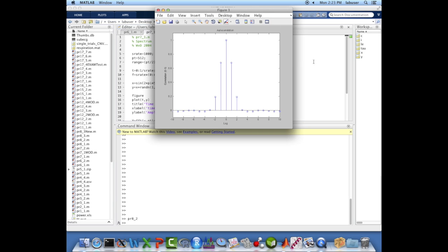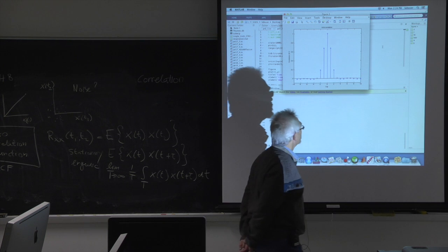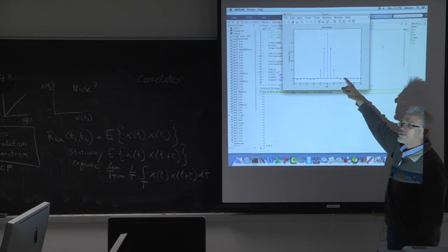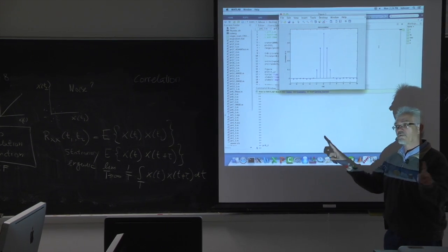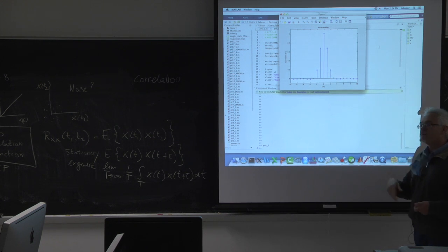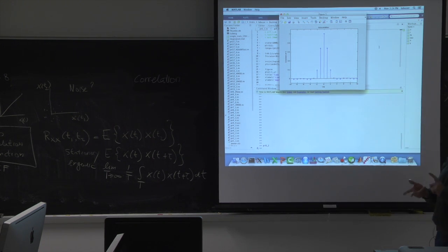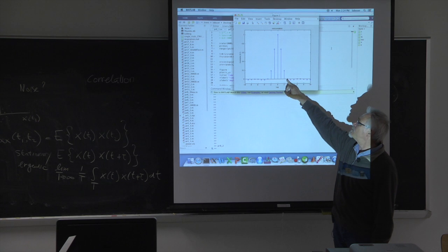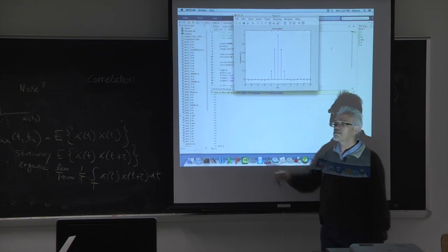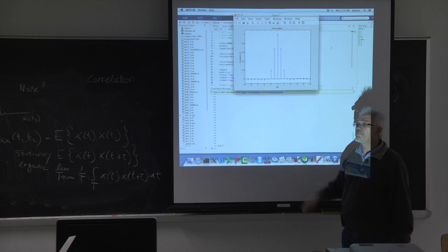If you run this program, it will compute, using the random command in MATLAB, the output of that time series and then look at the correlation. What it then computes is the correlation versus the delay. So here is the shift: one shift, two shifts, etc., in number of time points. You have discrete time, so you can shift it by 1 point, 2 points, 3 points, etc., -1, -2, etc. And when you do that, you see that most of the time the autocorrelation of y is close to 0, except in this area.